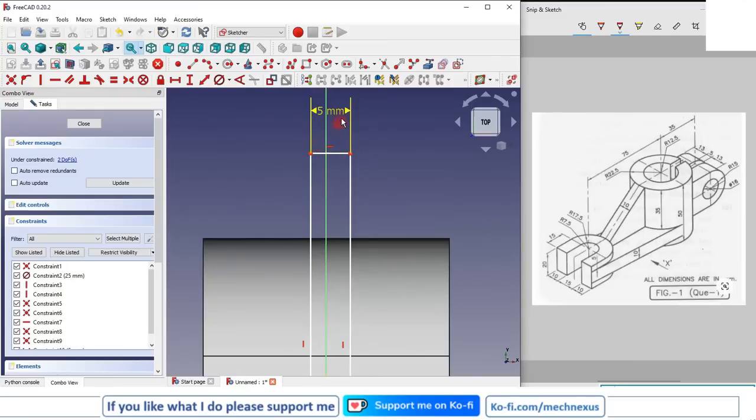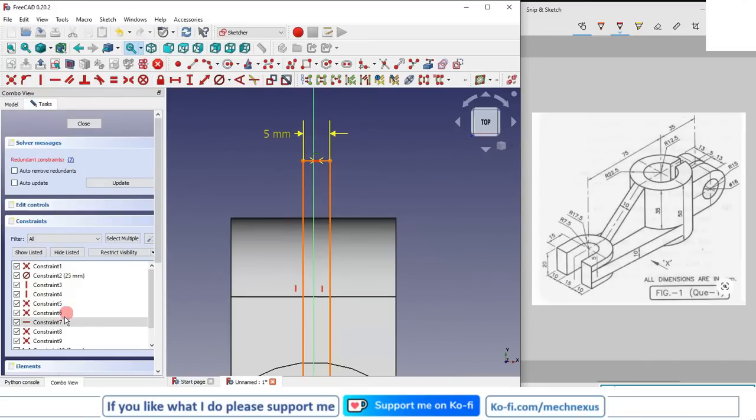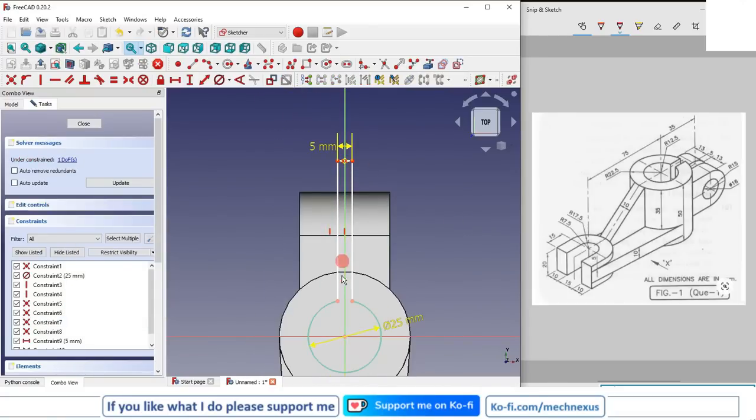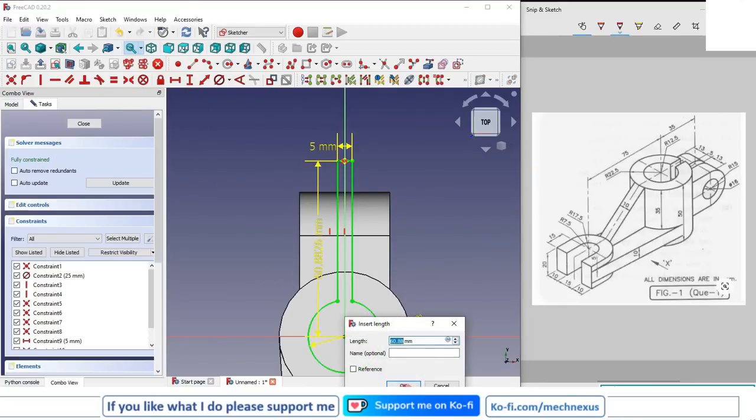and this would be the symmetric, so I will select on symmetricity. I will select this point and my axis. So here is a conflict, so I will delete it. This dimension does not have much importance because we are going to remove material, so we will give an approximate dimension, whatever it comes.